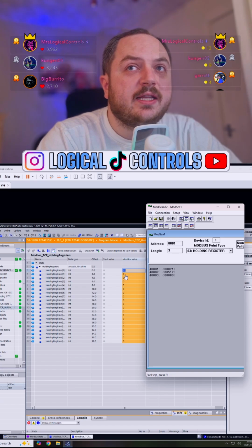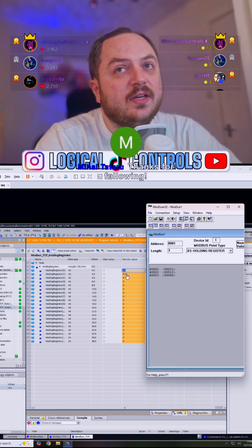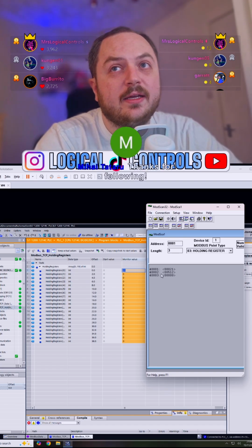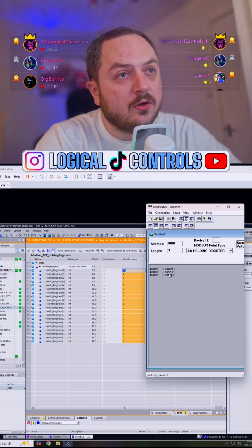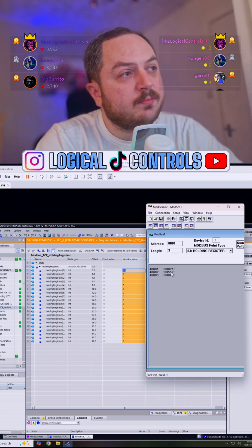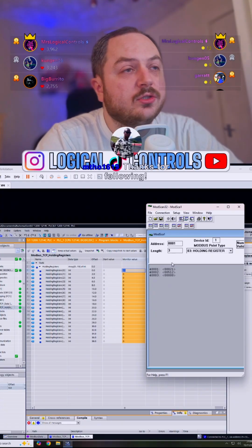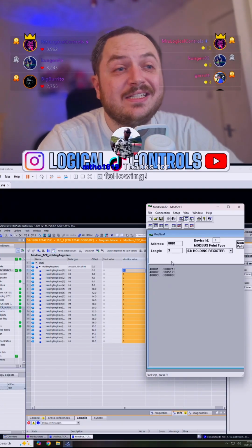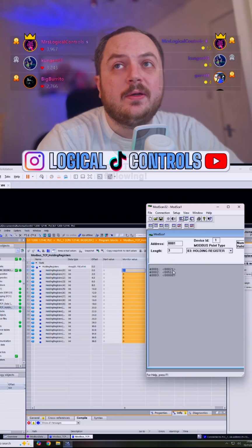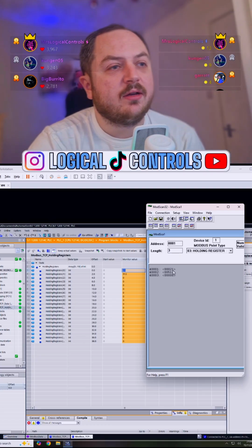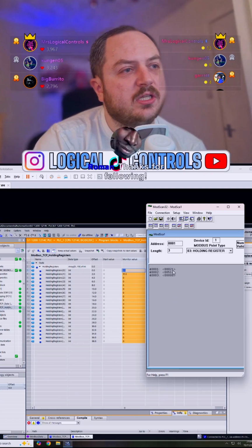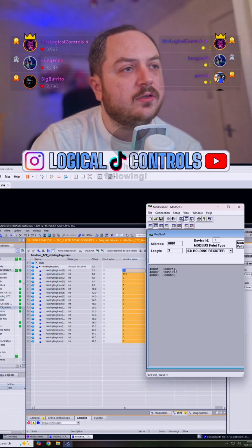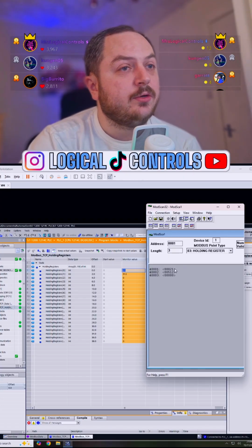You can see in that PLC that 512 is on and off pretty quick, but it doesn't go to 0 in the Modbus because the Modbus master is too slow at reading it. It's not set up to be very fast. Modbus isn't a very fast protocol, full stop. It's a very old protocol. It's been around like 40 odd years. I don't know about Modbus TCP itself. That's obviously a lot newer. That came around after Modbus RTU and ASCII.